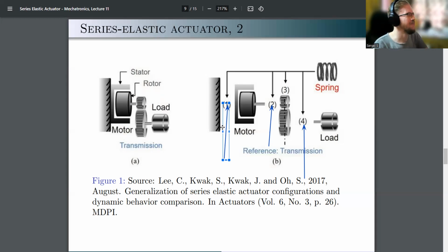Good question, because then your stator would not be rigidly connected to the rest of your mechanical structure, and your mechanical structure has this underactuated behavior, but it is possible, of course. And then you could try to integrate it somehow inside the gearbox, which I'm not going to comment on, but it's also possible. Some types of gearboxes naturally have some elasticity. For example, if we use, instead of gears, belts.